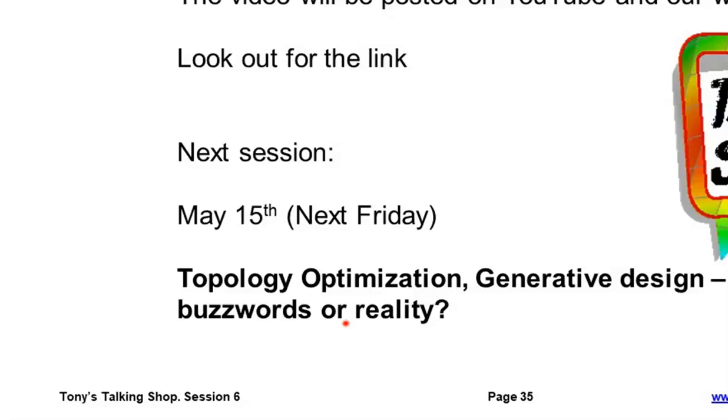There are other extensions to deal with more, as I said, like the Seeger method, but even that, I think, is dealing with larger regions of local plasticity. To have something which is shaking down into a nonlinear response overall, I think, again, that's outside my experience. So as far as we're concerned, it's just this local, as you said, it's a local correction factor. How do we play the magic trick to go from an elastic linear analysis to form the basis of even our strain life approach? It's that local behavior we're concerned with.